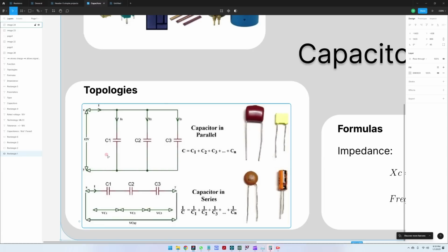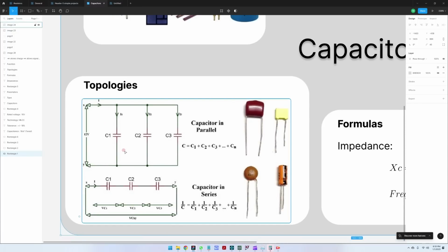Also, it is very common that, for example, you use a 10 decade drop. So for example, here you place 100 microfarads, then here you place 10 microfarads, then here 1 microfarad, because they would ensure different behaviors, also because of the ESR, and of course regarding the impedance, but we will discuss this a bit later.